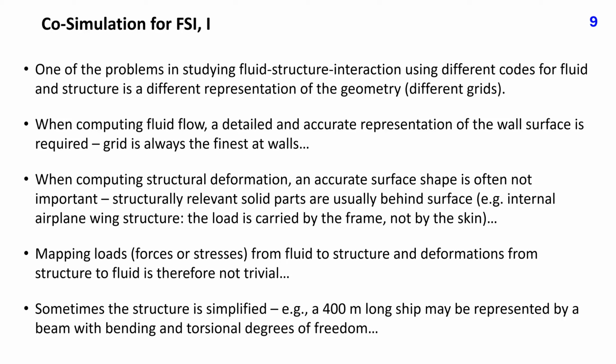Mapping loads, that is forces or stresses, from fluid to structure and deformations from structure to fluid is therefore not trivial. Sometimes the structure is simplified. For example, a 400-meter long ship may be represented by a beam with bending and torsional degrees of freedom. For the computation of flow-induced forces, no major simplification is possible.